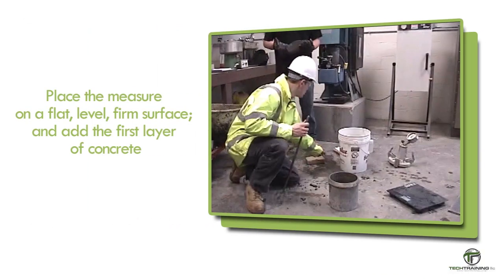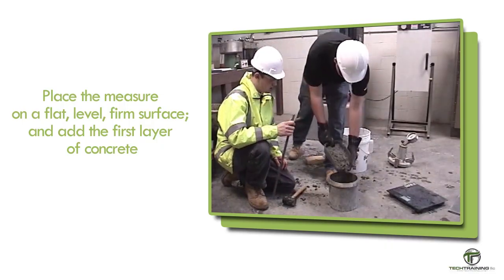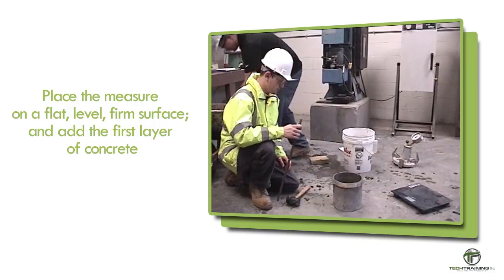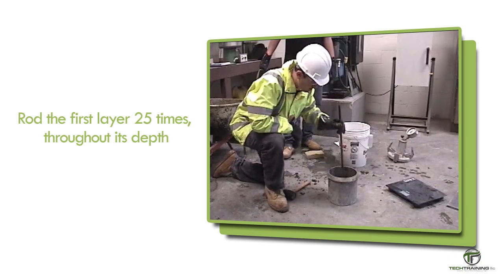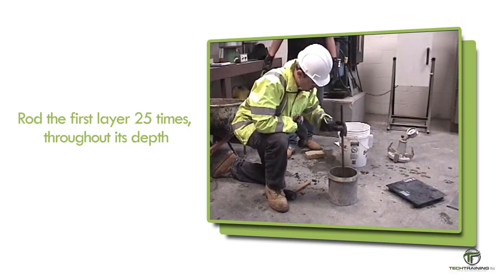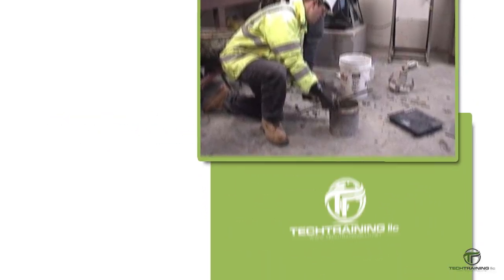Place the measure on a flat, level, firm surface and add the first layer of concrete. Move the scoop around the perimeter of the measure opening to ensure an even distribution of the concrete with minimal segregation. Since our measure is less than 0.5 cubic feet, or 14 liters, we will rod each layer 25 times. As always, we'll use the rounded end of the tamping rod. We'll rod the first layer throughout its depth.